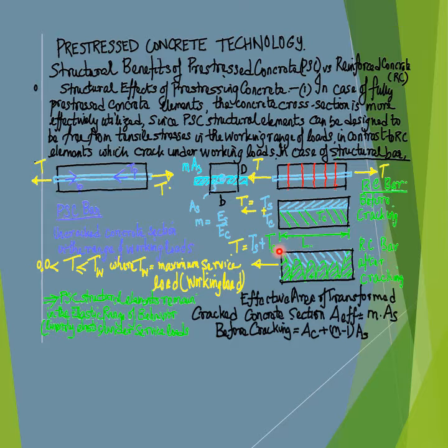that illustrates the distribution of the externally applied tensile force, capital T, between the cracked concrete, represented by the green shaded regions, and the share of the externally applied tensile force, denoted as capital T subscript S, that is resisted by the concentric steel bar.